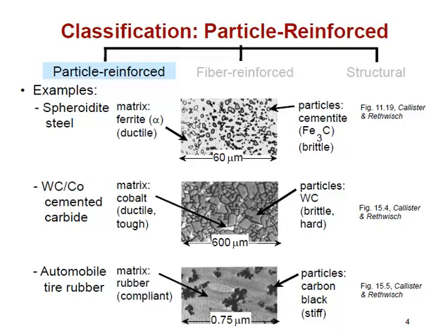On the ceramic side, not that cementite is going to act like a ceramic, but a little bit more targeted type of high temperature ceramic, tungsten carbide. This is a precipitated tungsten carbide in a cobalt matrix. This is going to have very, very high thermomechanical properties, great for high-speed machining, very corrosion resistant in certain environments.